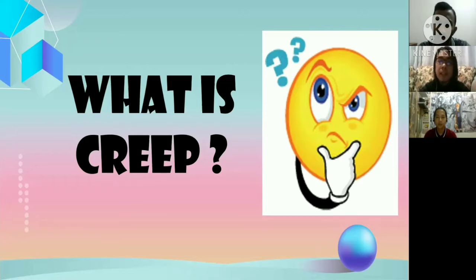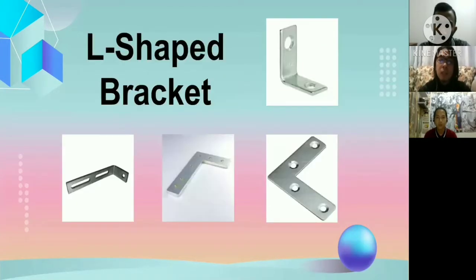Other than that, there are five factors that affect the rate of creep. The first is the load, the second one is the temperature, the third is composition, the fourth is grain size, and the fifth is heat treatment. So with that knowledge, for the first part, I would like to invite our panel, Mr. Muawidza, to tell us some applications of creep in real life.